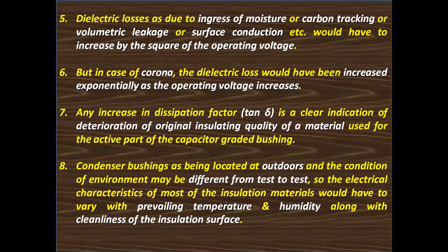Number five, dielectric losses due to ingress of moisture, carbon tracking, volumetric leakage, or surface conduction, etc., would increase by the square of the operating voltage.